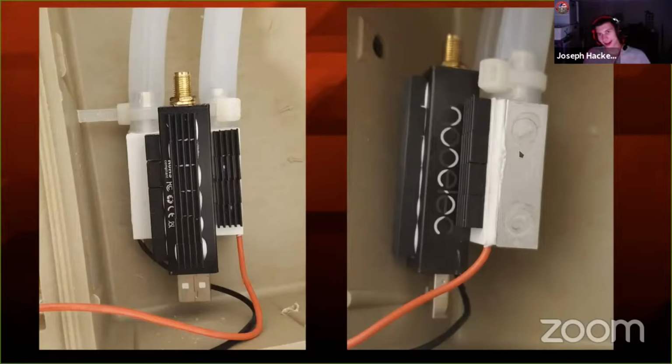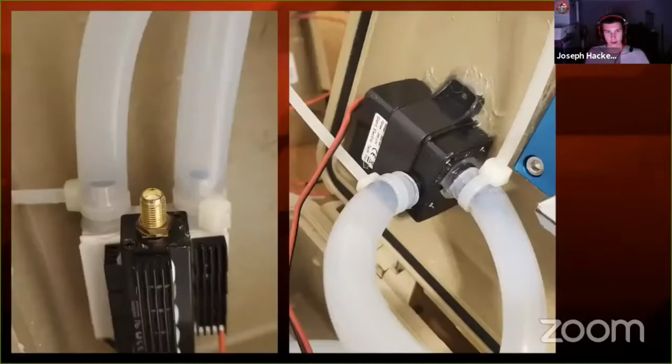On the other side of the Peltier, I've got this aluminum water block. As you can see here in the left picture, it's got these 2 little holes on it, and you can stick a hose on there and actually pass water through it, and the water or whatever else you're using will carry the heat with it. I used water because that's all I had, but you can also use oil of various kinds, and they also make special thermal conductive fluid.